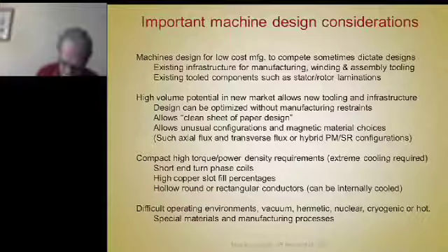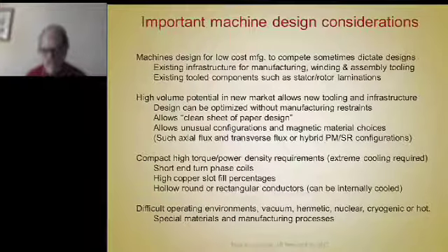But manufacturing people don't like that because it's slower, more tedious, and much more difficult to insert these shorter coils into the slots of the cores to get them over the teeth, to span the number of teeth they have to. So if it's automated machinery, you can have jams in machinery. You can even break part of the tooling by trying to put short, tight coils in that just barely fit over the teeth.